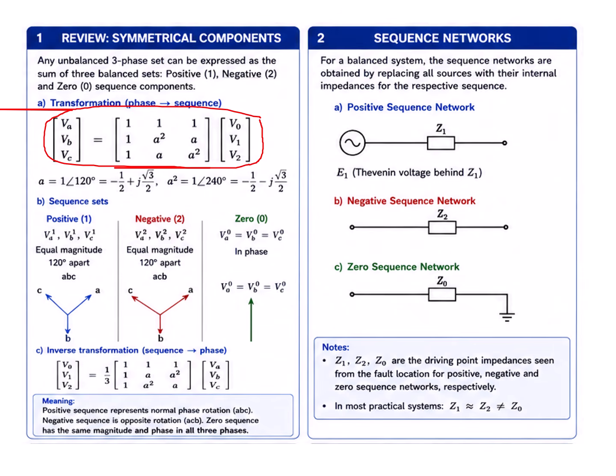The positive sequence is VABC, and we will have this. Again, we have a negative sequence. In the negative sequence, we have this signal with equal magnitude, but in a different sequence. Here it will be B and A, so this is 120 degrees, and it becomes ACB. ACB versus ABC: their sequences have the same magnitude but different phase sequence. So we can invert that to get the phase sequence.